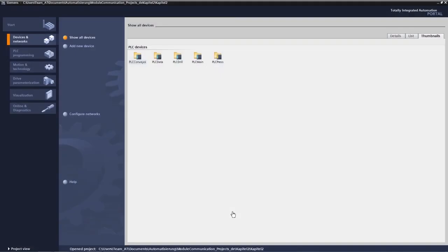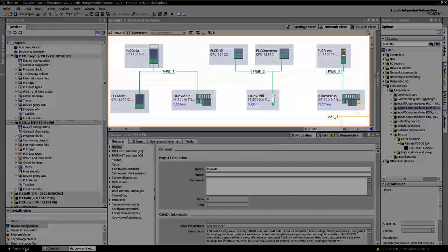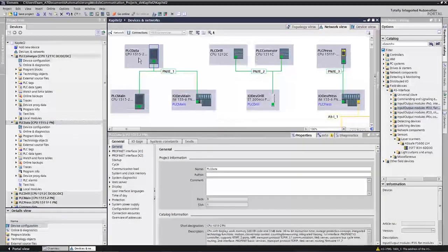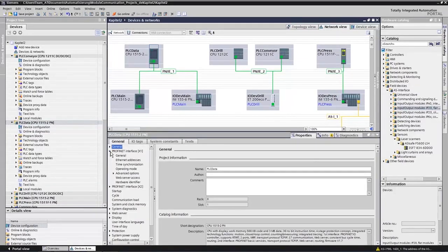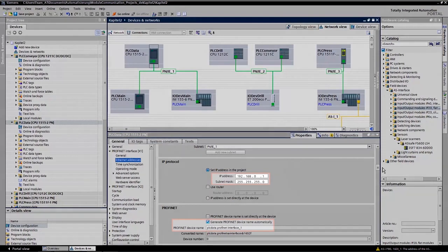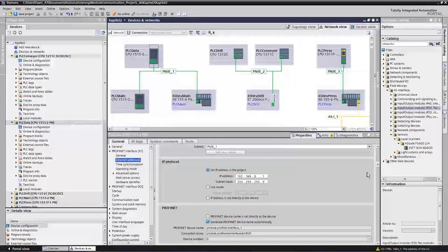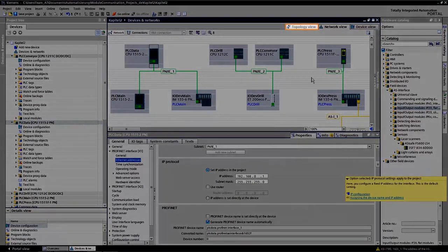We started with Profinet functions and are now focusing on configuration within the TIA portal. As you can see, some Profinet devices have already been commissioned. The TIA portal has automatically assigned addresses and device names. You may rename these items at any time. To create a ring with Profinet, switch to the view Topology.